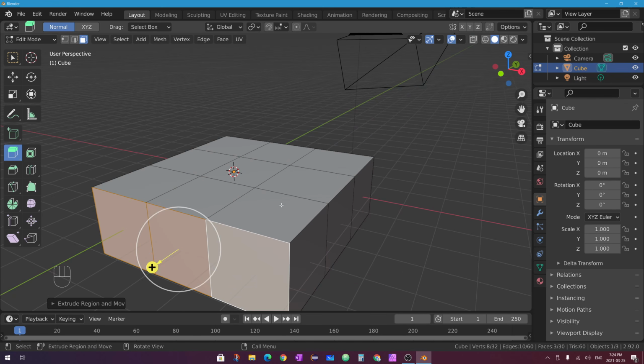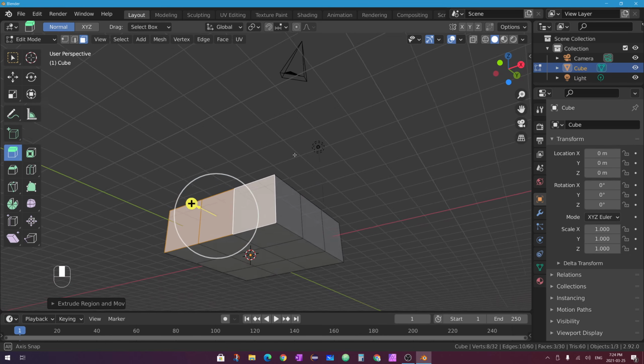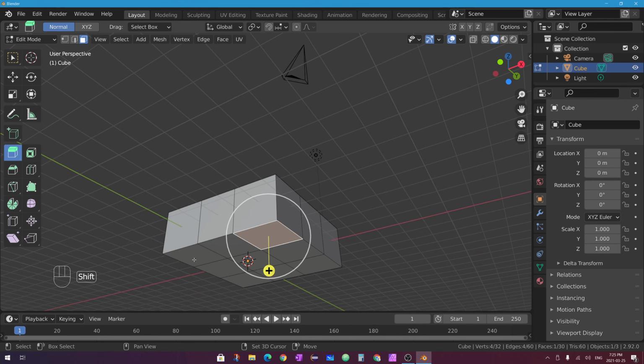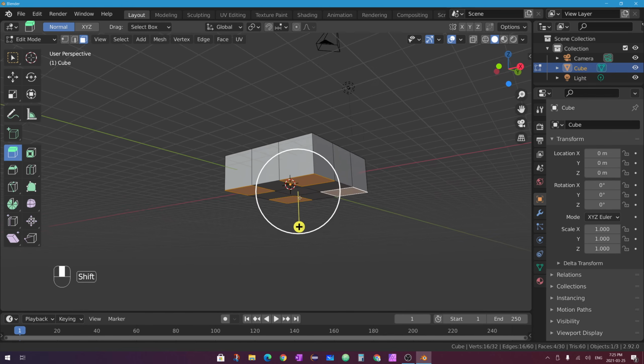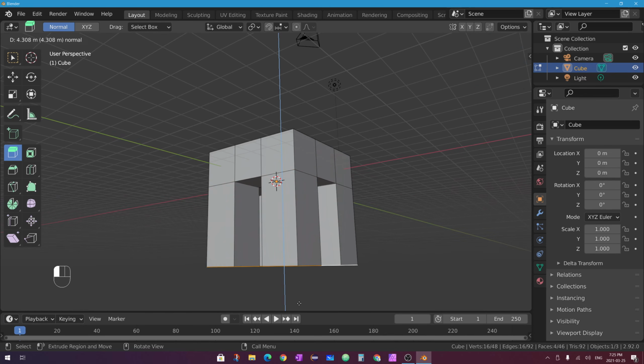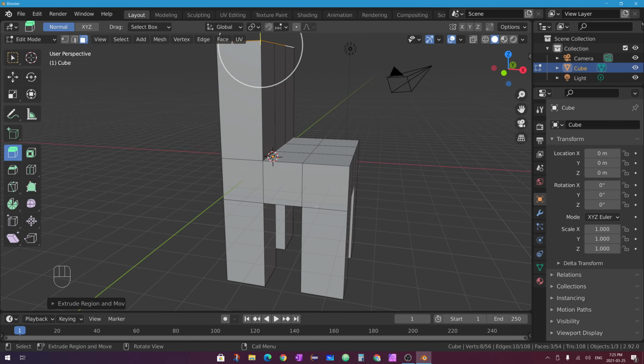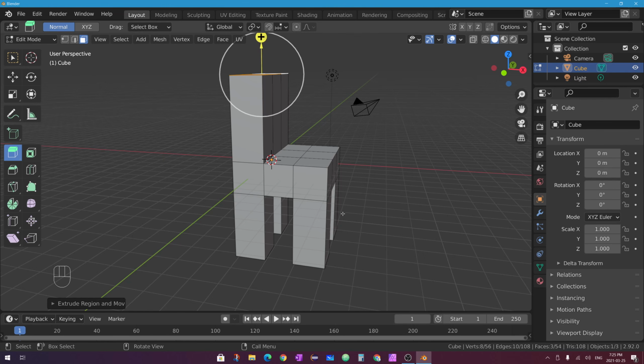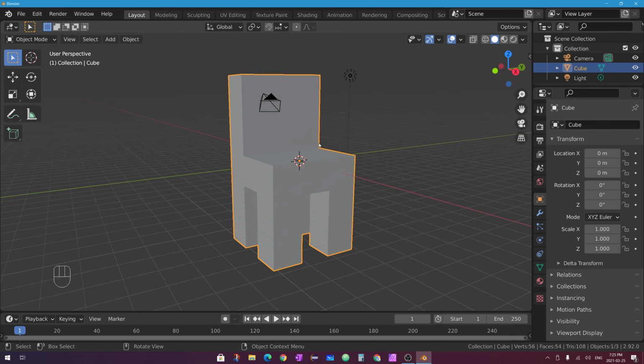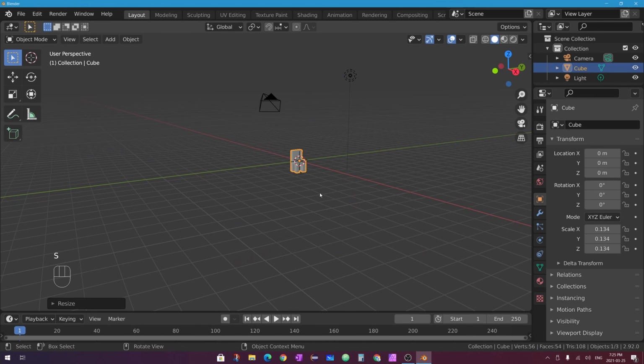You can see if I want to create something like a chair, a simple 3D object, it wouldn't be too hard. I can continue this. I can select the corner faces. I'll hold Shift on my keyboard to do that, and I can extrude down. I'll orbit my scene and pan over and grab those 4 on the bottom and drag them down. And I'll grab 3 in a row on the top and I'll drag these up, and you can see I have a chair. And if I'm happy with my chair, I can go ahead and go back to object mode, and my chair is done, and I can go and work with other objects, or I could scale my chair down to be a more realistic size.